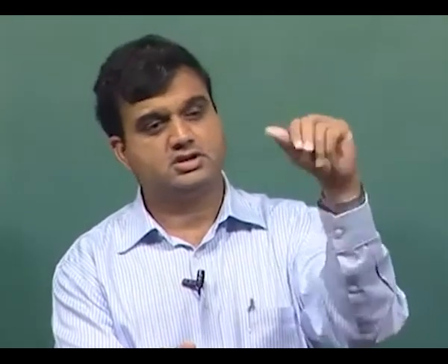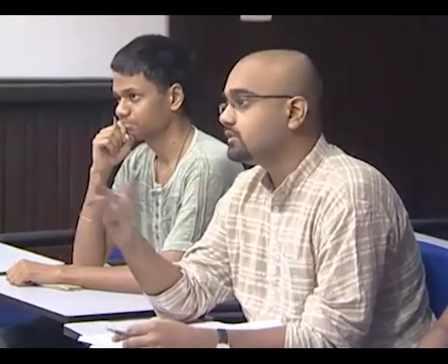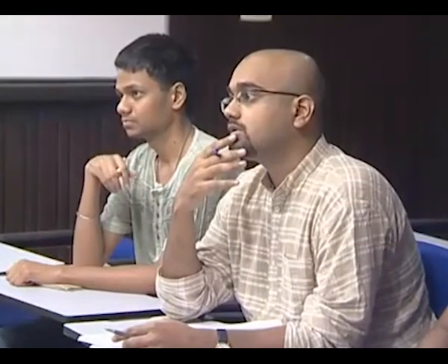What do you mean? Charge is dependent on the capacitance, and the capacitance is dependent on the effective distance, which will change with the vibrations. It will change with the vibration. In what sense? If I am putting a pressure, regardless of whatever frequency it is, let's say it has a value of 5 newtons per meter square, then my membrane will just move accordingly by the same amount. It's a pressure wave, so accordingly it will vibrate, and because of that the effective distance between the two membranes will change with a frequency same as that of the pressure wave hitting the entire thing.